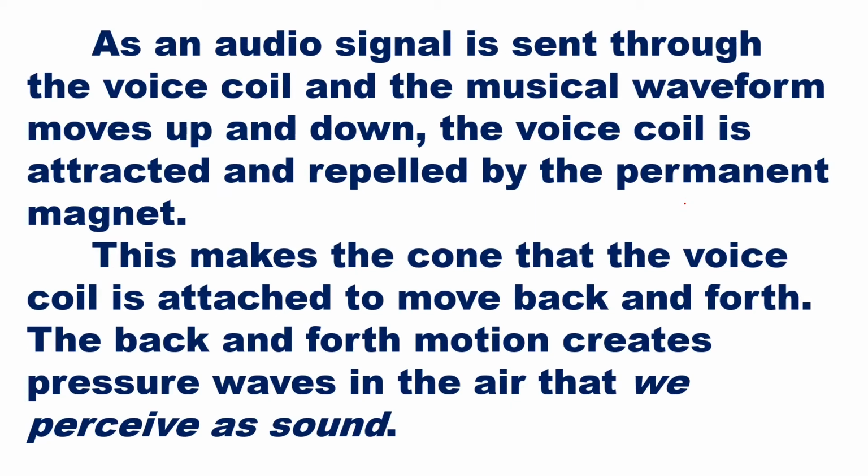As an audio signal is sent through the voice coil and the musical waveform moves up and down, the voice coil is attracted and repelled by the permanent magnet. This makes the cone that the voice coil is attached to move back and forth. The back and forth motion creates pressure waves in the air that we perceive as sound waves. So this is how your electrical signal is converted to sound energy.